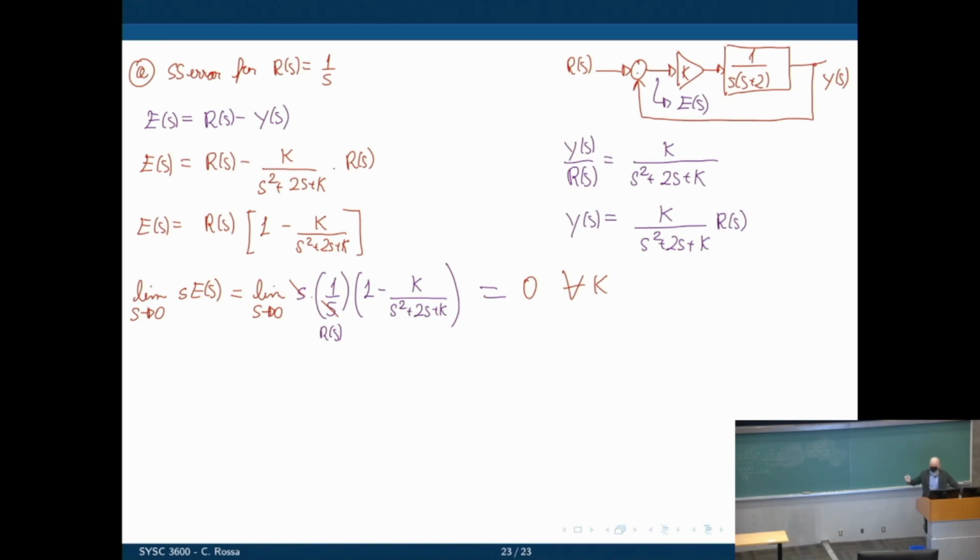It is easy to understand. If you put a negative K here, we are now making the error increase instead of decreasing. We are making the robot go in the wrong direction, so you're always increasing the error instead of decreasing it, and then it just blows up. It's a positive feedback loop.